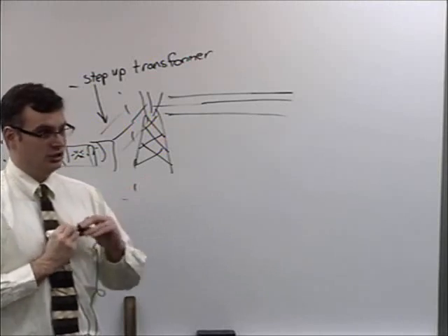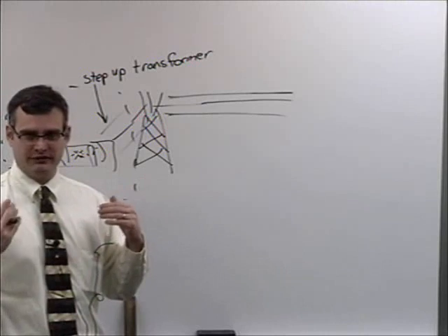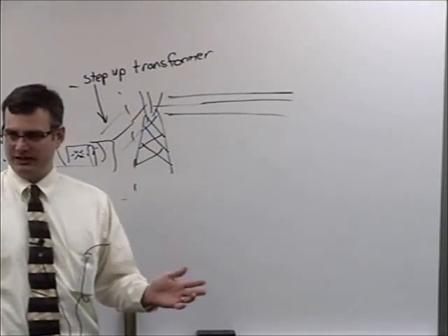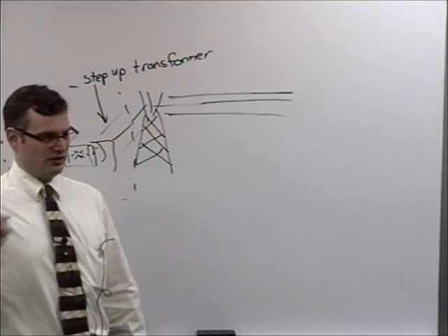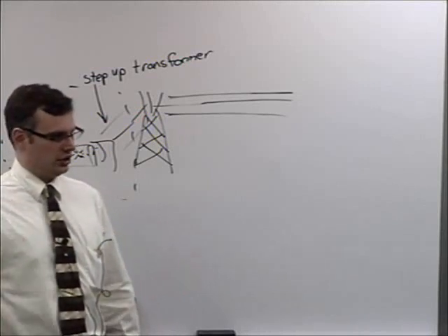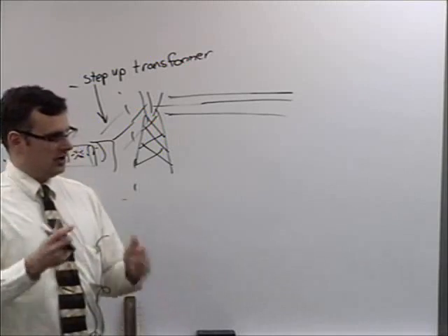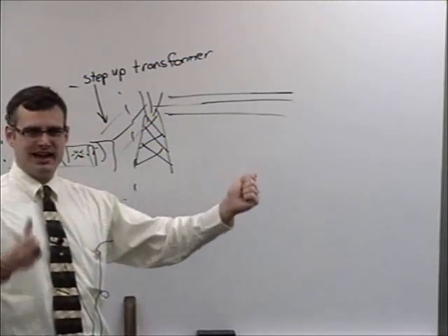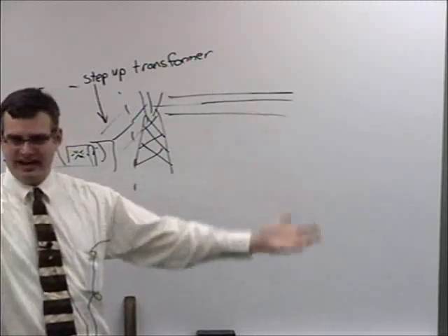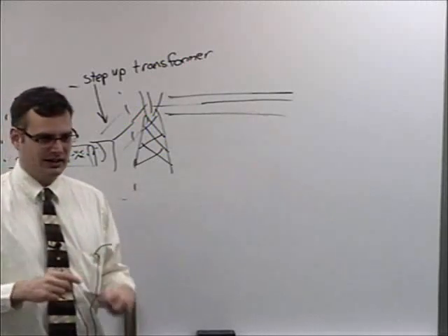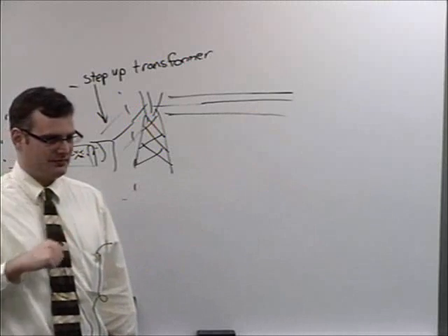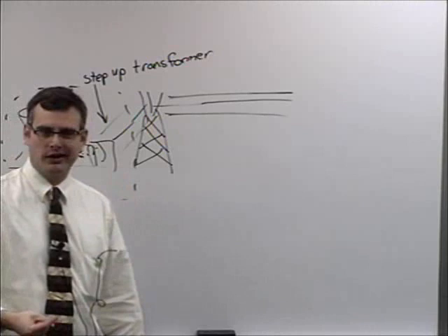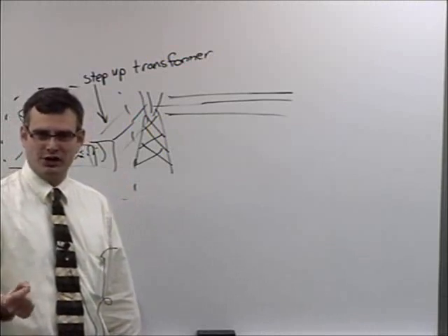That's right. Remember, the product on a transmission line, product of voltage and current, is always watts. That's the amount of power that you're transmitting. So, generator generates a certain amount of voltage and current, certain amount of power. You want to distribute the voltage and current in such a way so that voltage is maximized and current is minimized. As we'll learn again, in the lossy section of the transmission line unit, your principal losses in this particular kind of transmission line network is from conductive losses on your cable.